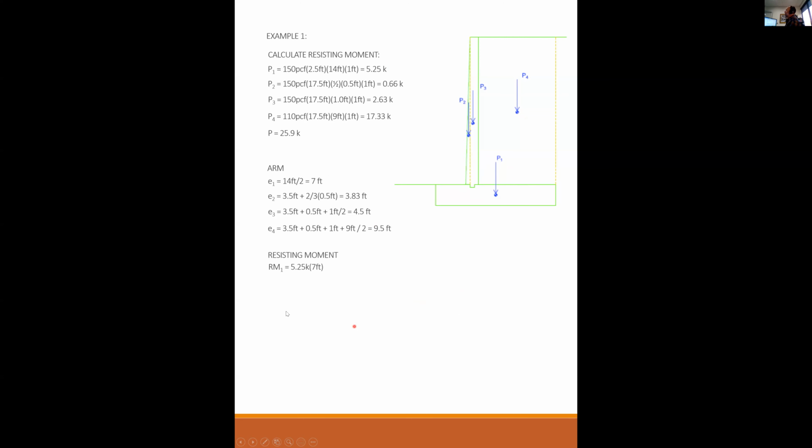So my resisting moment is, you add them all together, 5.25 times 7 is 36.8. 0.66 times 3.83 is 2.5. 11.8. And the soil, that's the big one, 17.3 times 9.5 is 164.6.